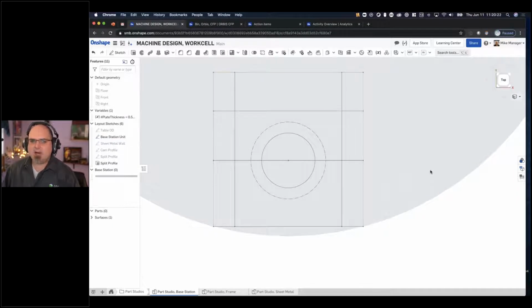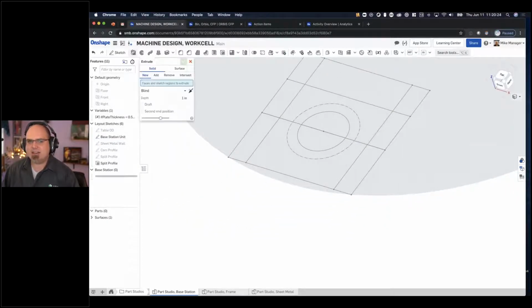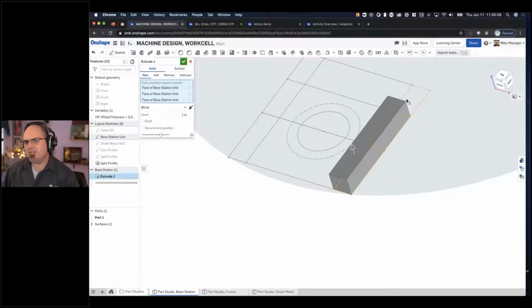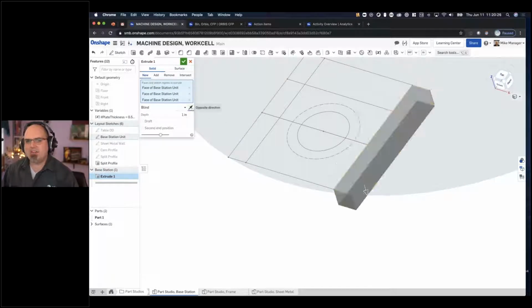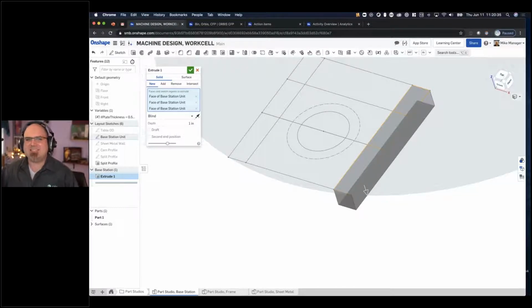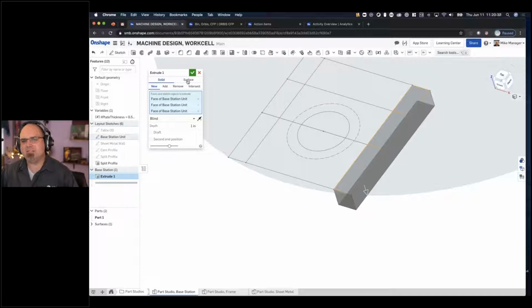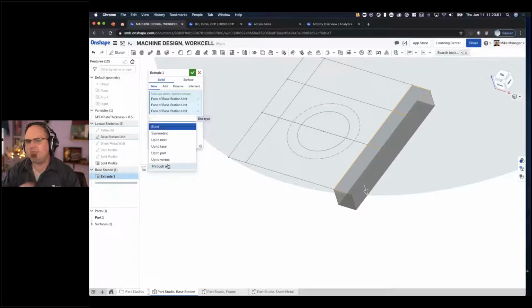Then I want to make 3D models from that sketch, and I have all of the normal parametric tools that you're used to seeing. Here I have an extrude. You notice the ribbon of tools is very Spartan, right? It's because the tools themselves are very deep. Solid and surface modeling. You can create new parts. You can add the parts, cut, even create Boolean intersections at the same time with one fantastic tool. But of course, all the end conditions, all of this will be very familiar. You will feel comfortable when starting in the Onshape system this way.